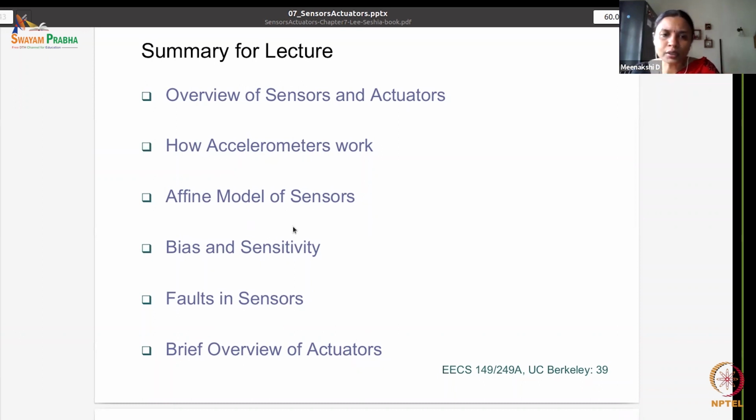Interrupts can be viewed in two ways. One is to say that they correspond to sporadic inputs. It doesn't come so regularly that I need to run periodic polls to read it, but it comes sporadically. So I view it as an alert: wait for an interrupt, and then read it. Or there could be an error, and then for that also I use an interrupt.